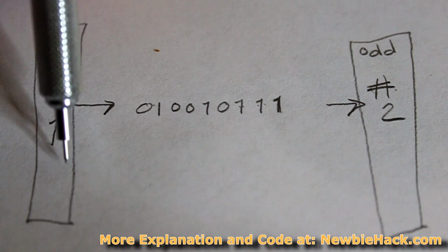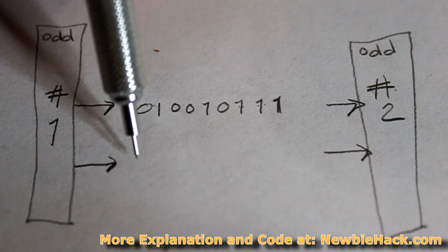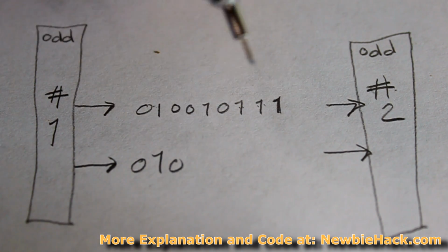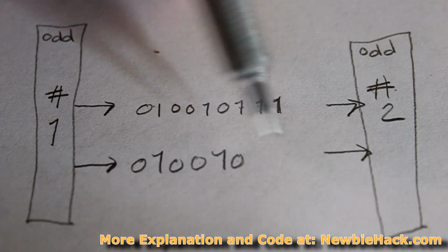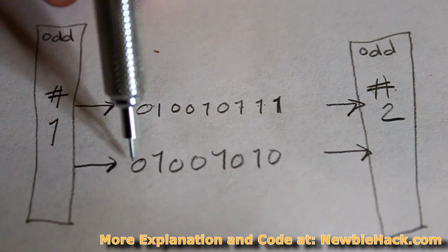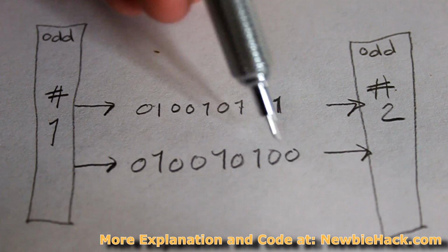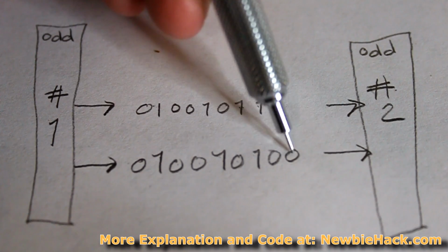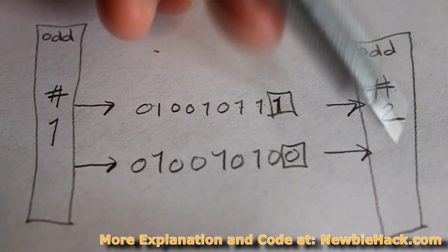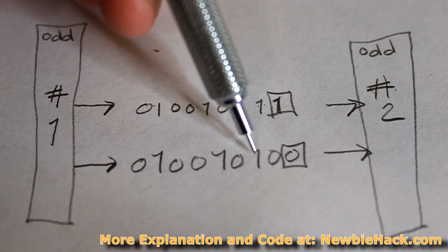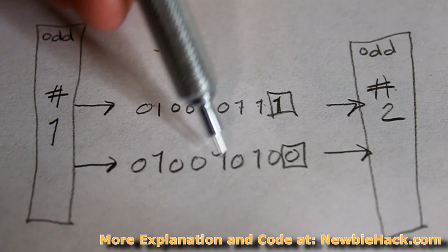Actually, let's do another odd so you can see the other case, putting a 0 there. So if there was an odd number: 0, 0, 1, 0, let's see, 1, 2, 3, 4, 5, 6, 7, 8. Okay, so there is already an odd number within the data bits, so we better put a 0 at the end because we want to maintain an odd number. So the transmitter will set that parity bit, and then the receiver will make sure that it is a 0, and it'll check with the number of 1s in here because it's set to odd, and it's counted 3 1s.